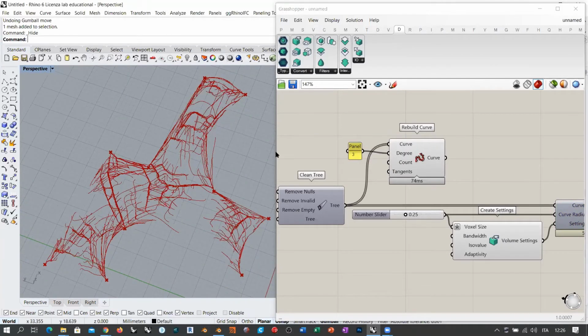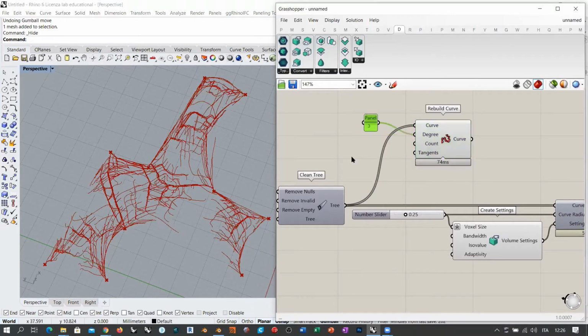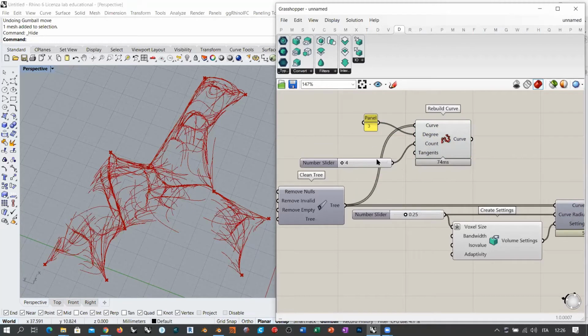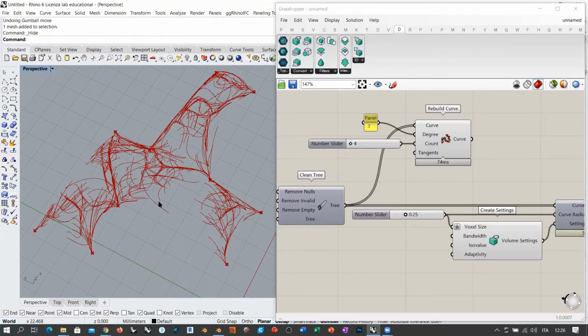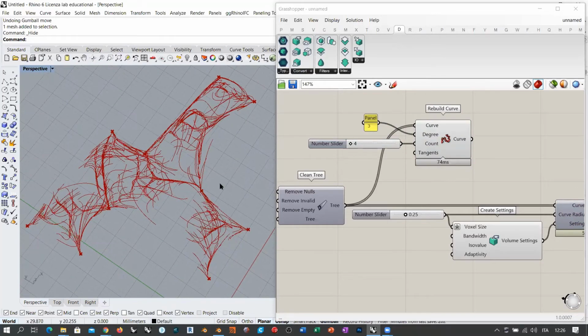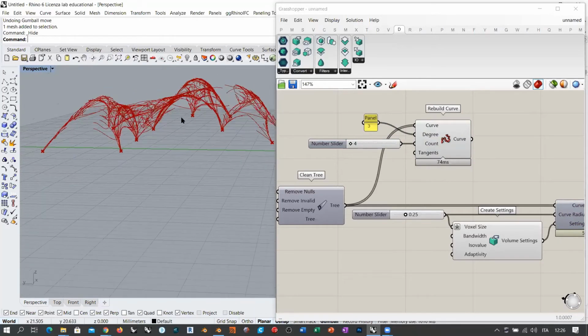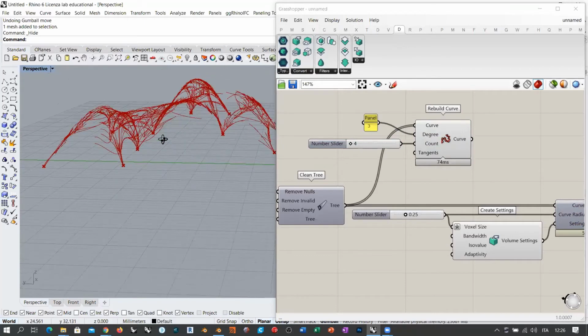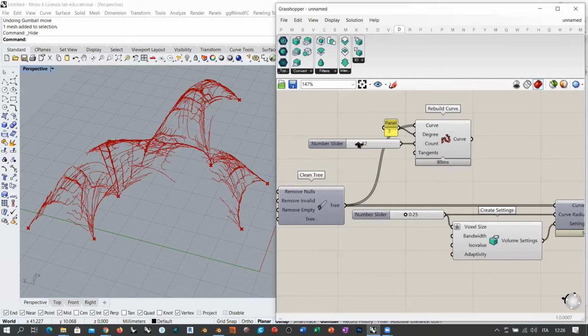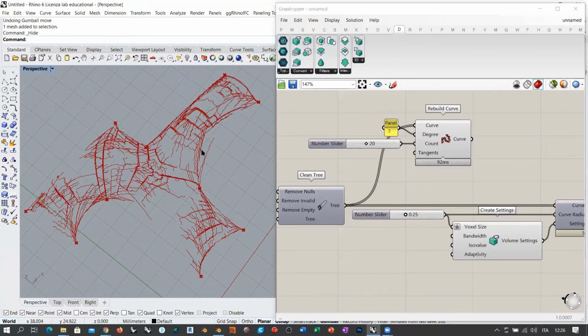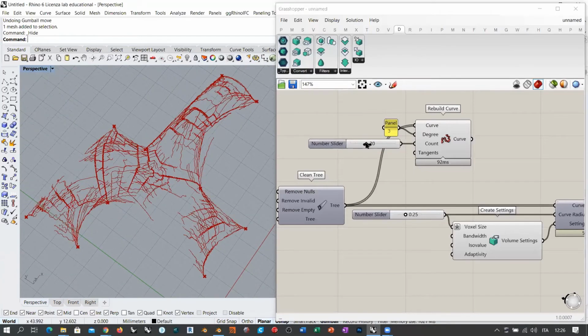They were polylines, by the way. And let's grab an amount of control points between 4 and 50. If I use 4, I smoothen these curves too much, as you can see. It's always nice as a design, if you think about it, but it's less relevant. And it also starts to cut through the mesh or just disconnect from the mesh too much because of the smoothing that is happening here. So if we increase the amount of control points, we start to recover the original fiber system shape.